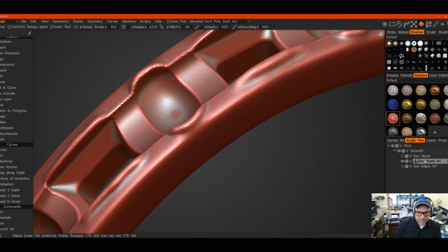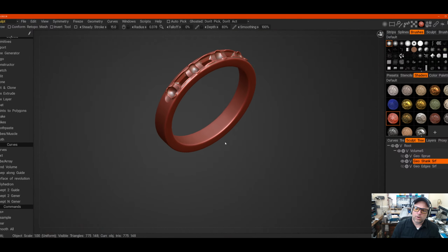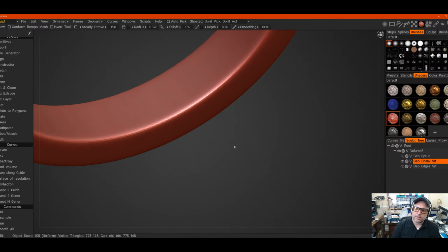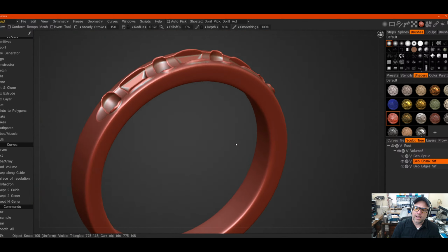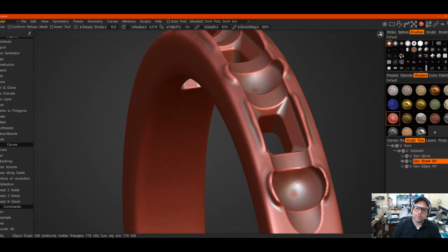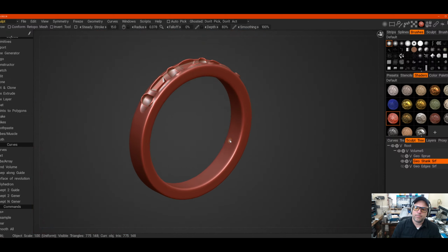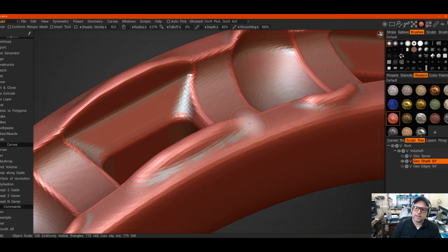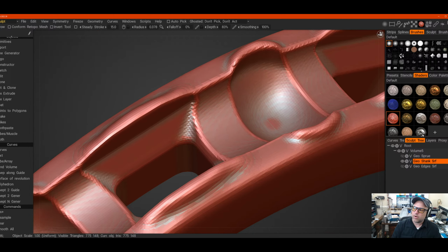To the people that just always make the voxels smaller, I don't like that, because the camera gets really wonky in 3DCoat when you're working on something tiny. Again, this camera was made to work on something the size of a car. So I find that my camera becomes really unusable when I'm dealing with something really tiny. So I do want this to be the size of a car.